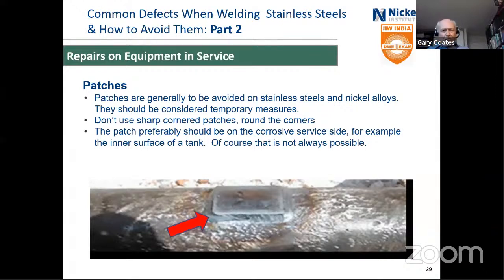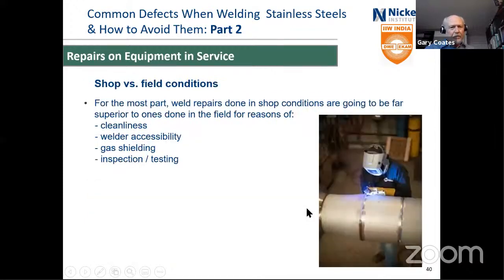Of course, if it's a pipe, that's not possible normally, but always use rounded corners on the patch. Don't put sharp corners there because those are stress risers where you can easily end up with fatigue. So patches are possible, but really should be considered only a temporary measure.